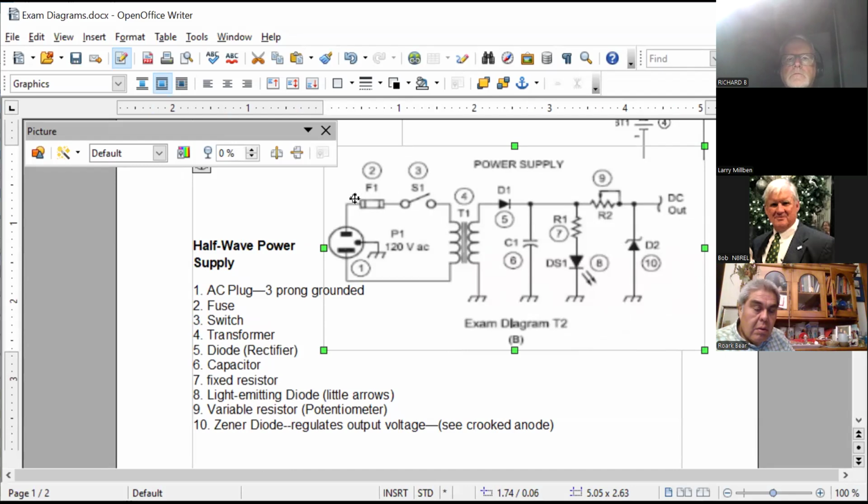Now we have the sine wave here. The diode will only let the positive part of the sine wave come through. So instead of having this like that, it's going to go this, a space where the other part of the wave is supposed to be, and then another hump, and another hump, and another hump.